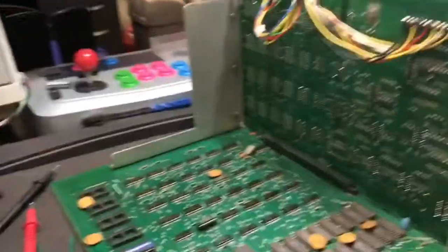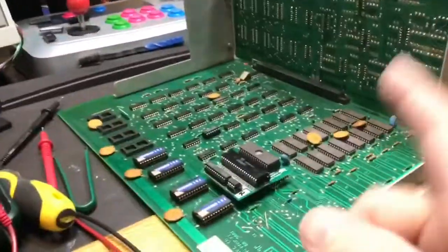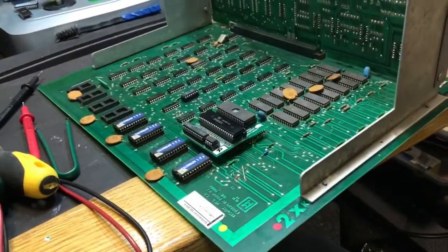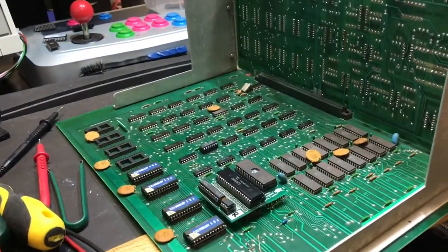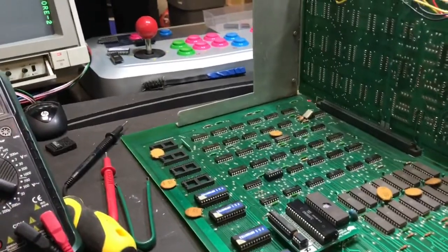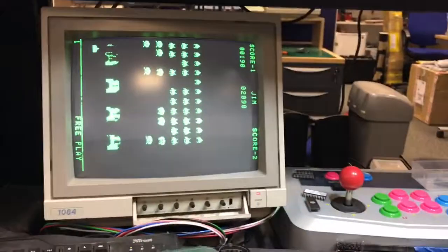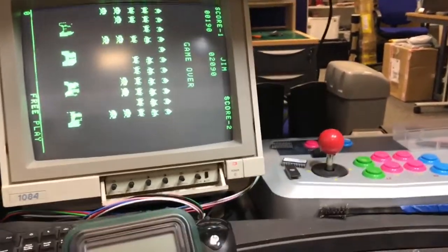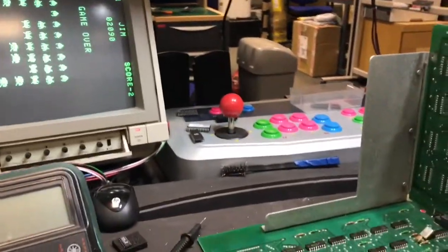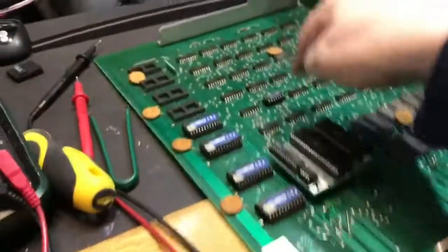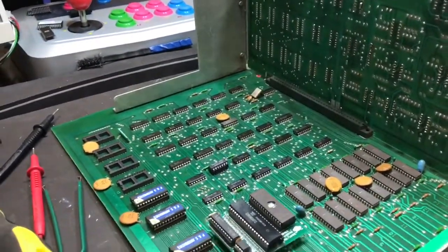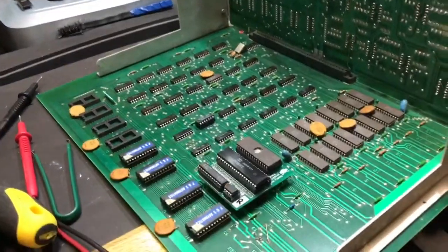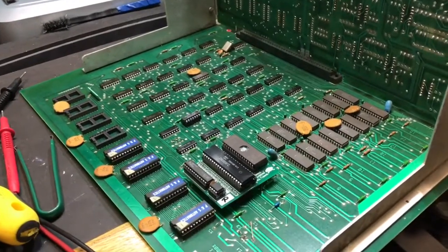Well, there's another Space Invaders repaired. I'm going to put it back in the cab later this afternoon, just to make sure that the credit board and everything works. But I'm pretty certain that the reason the customer reported the credits just kept cycling upwards and upwards like crazy was because of this stuck interrupt section here. I'll write the whole repair up in our log database. But ultimately, I believe that one's probably fixed now.